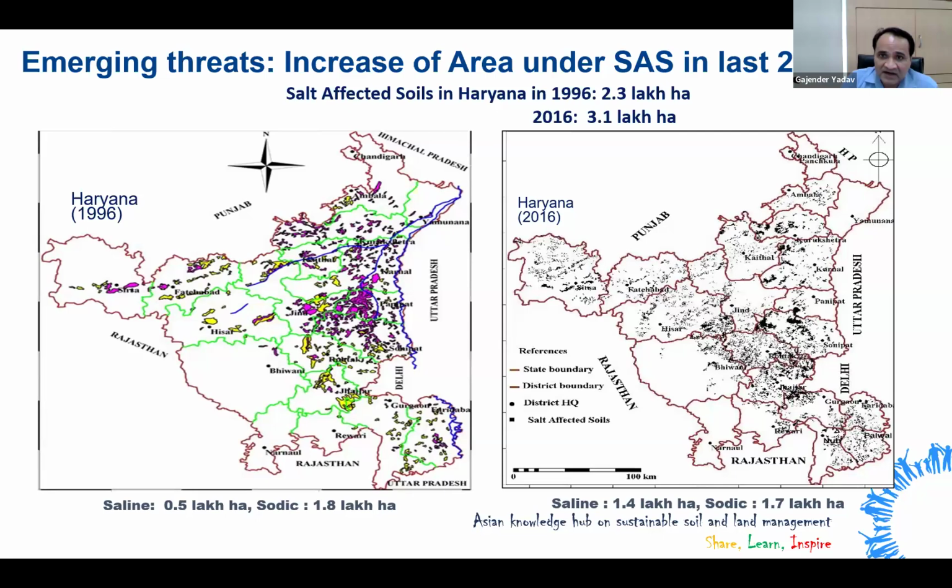Apart from all our efforts at salinity management, we have pilot projects on the implementation of subsurface drainage for salinity management. And we have been able to reclaim more than 2 million hectares of sodic soils of the Indo-Gangetic plains by using gypsum. But still, the salinity problem is increasing due to various reasons: the increasing irrigated area, climate change, and resodification and desalinization.